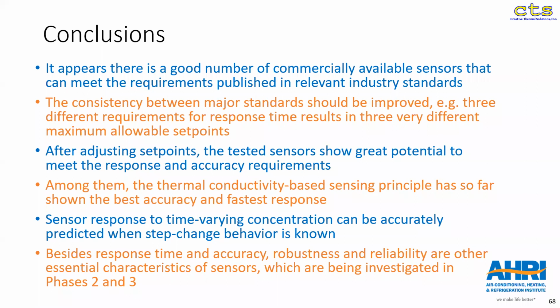Doesn't mean that it couldn't be achieved with any of the other ones. The sensor response time to time varying concentration we have shown can be accurately predicted. So this is good because we don't need to do all of these experiments. We only need to do the relatively simple step change. Once that is identified and characterized, then we can predict how the sensor would behave in real life.